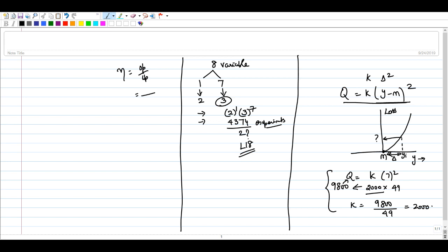So virtual shell is another version. If you are using the same part, yeah, for virtual you need to apply the idea, which remains the same, provided it is a separate part. You apply these three conditions to that particular part, and even if the same part is repeated 3 times and it satisfies these conditions all the 3 times, then they will be considered as the theoretical minimum number of parts.